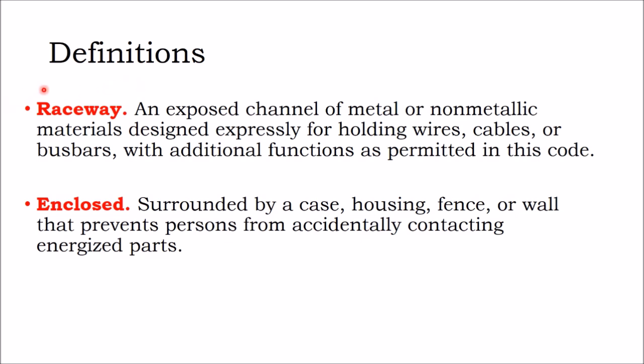Let's define a raceway: an exposed channel of metal or non-metallic materials. So a raceway can be metal or non-metal, designed expressly for holding wires, cables, or bus bars. It has to be listed for purpose, or if it's not listed, it's not saying a raceway needs to be listed.